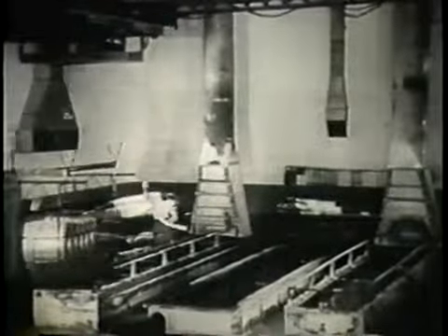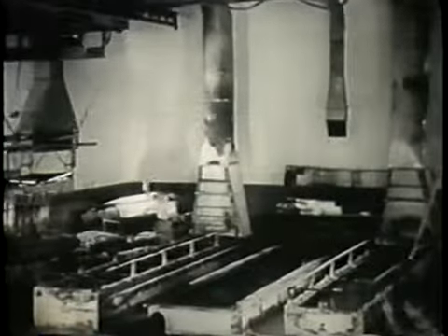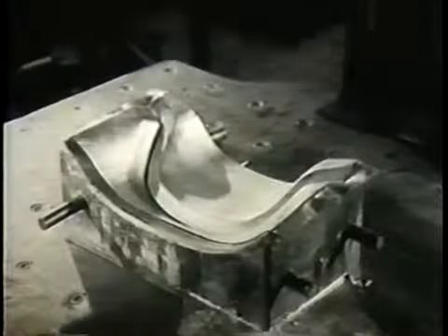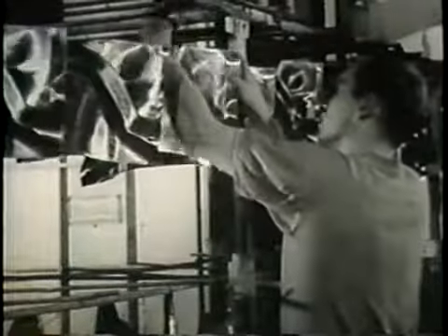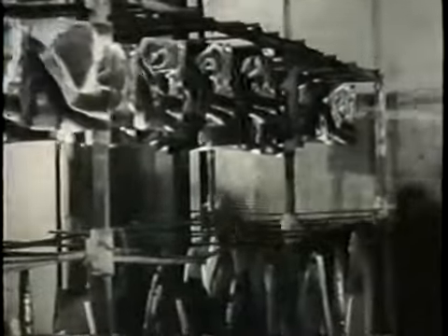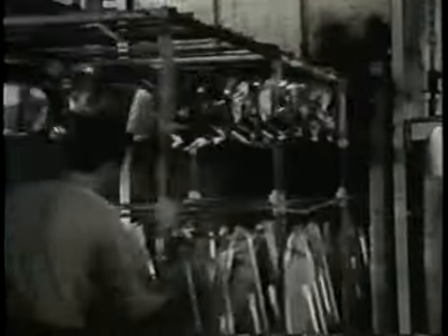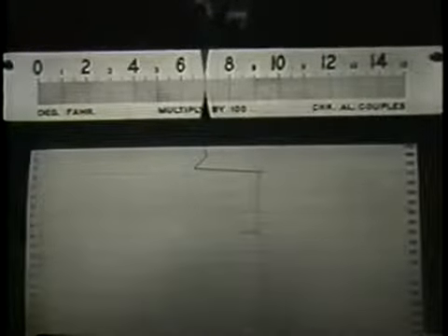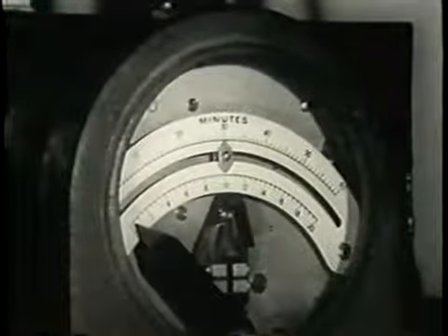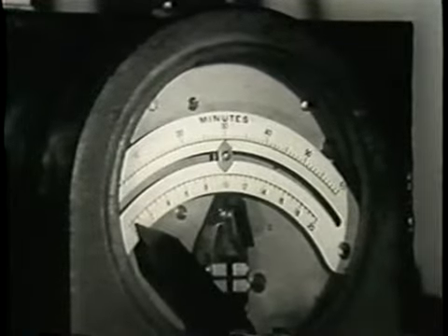If an aluminum alloy part has been strengthened through heat treatment and then strain hardened in the course of a forming operation, the effects of cold working and part of the effects of heat treatment may be removed by partially annealing the alloy in an air furnace. The partial annealing is performed at approximately 700 degrees Fahrenheit. The metal is kept in the furnace for about 30 minutes and then is quenched.